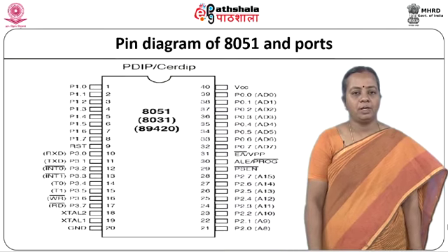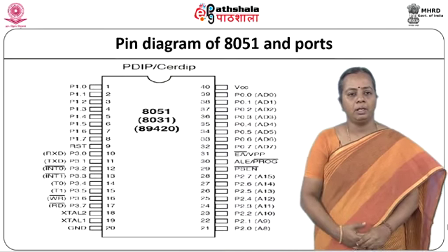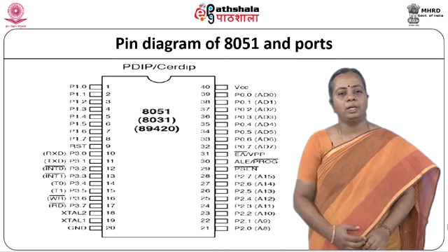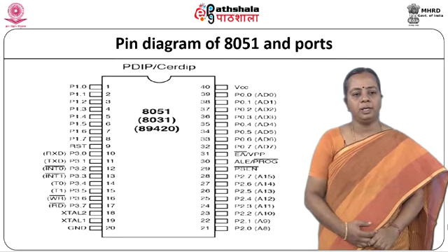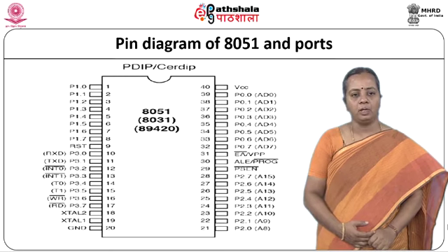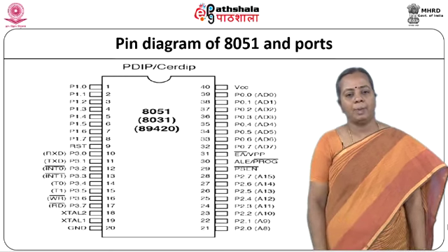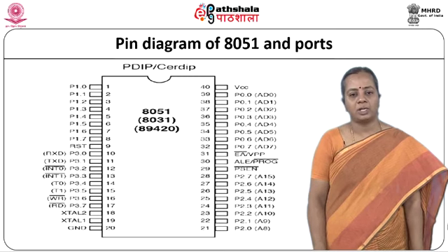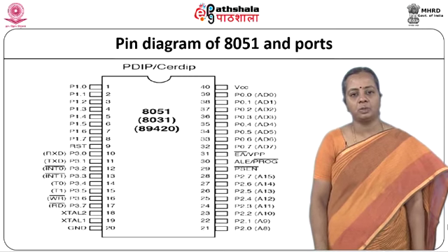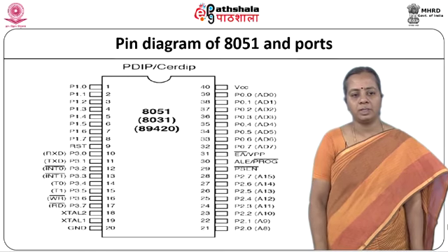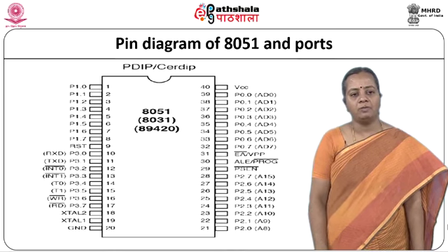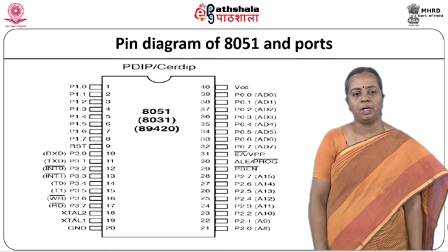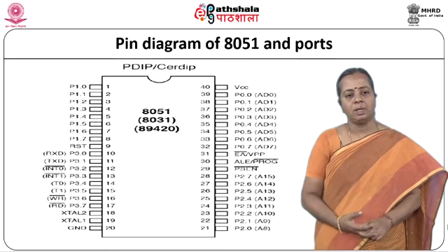When you look at the 8051 microcontroller, it is a 40 pin chip. In that 40 pin chip, the 40th pin and the 20th pin are VCC and ground, and we have 4 parallel ports. 2 of the ports will be used for sending addresses as well as data, receiving or sending data to memories or different input output devices. The other 2 can be used for interfacing with input output devices, and one port is special, it can be used for input output as well as for some special purpose.